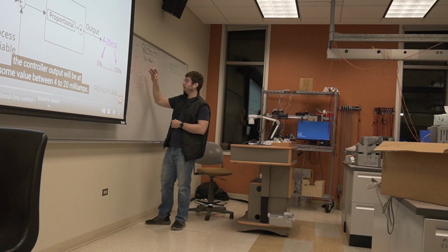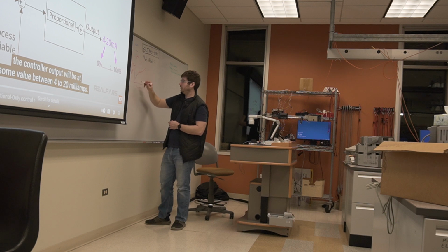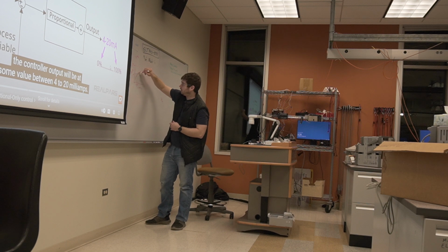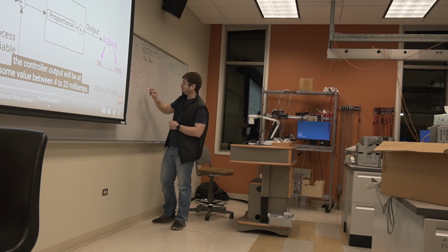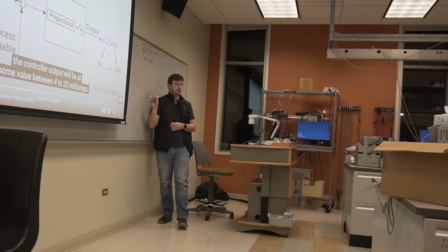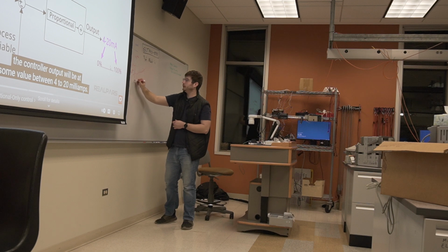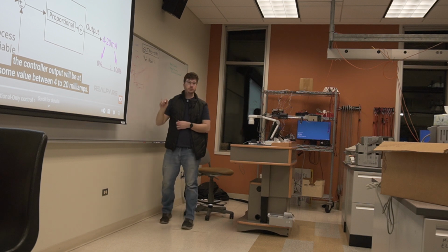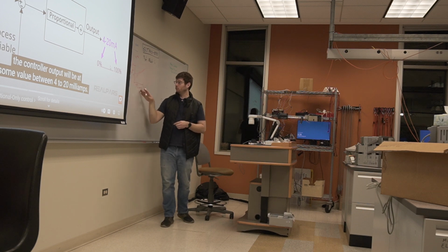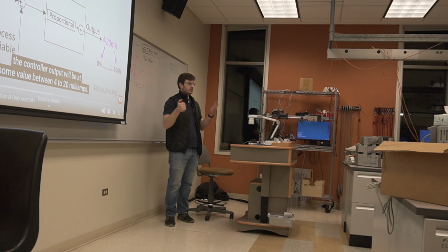So similarly, this is given to us by the manufacturer. We might also know that down here at like 1.8 volts, things are 25 degrees Celsius. And anywhere along this range, we more or less can figure out what voltage is between what temperature, right? If this was perfectly linear, it would be really easy to tell. It would just be a simple y equals mx plus b. For a given voltage, we could figure out what temperature we're seeing from that sensor.